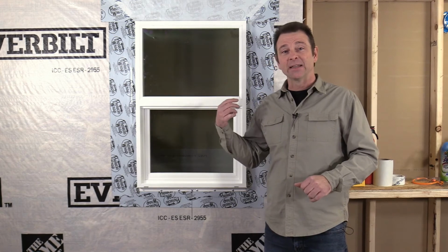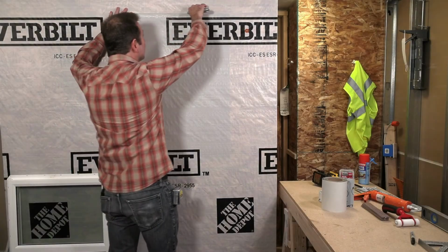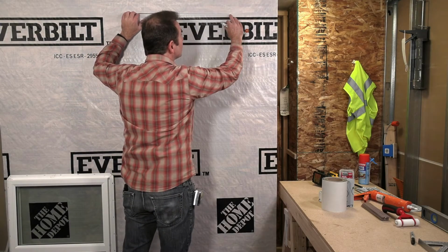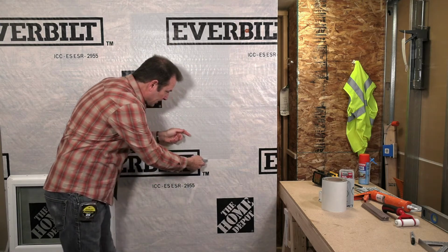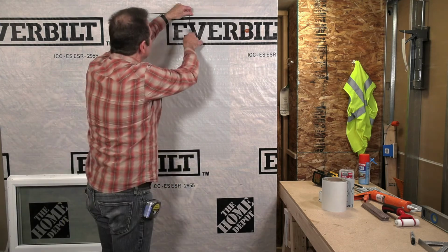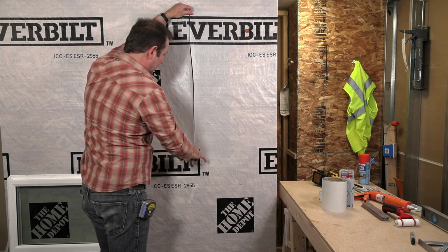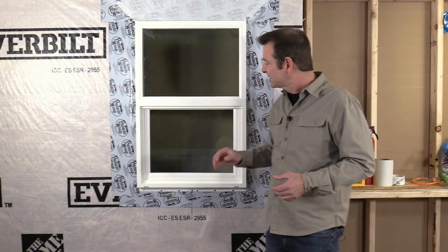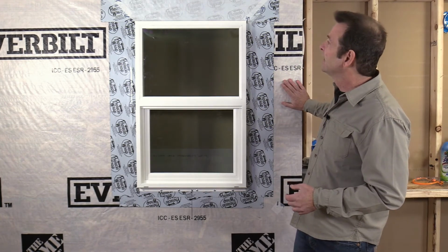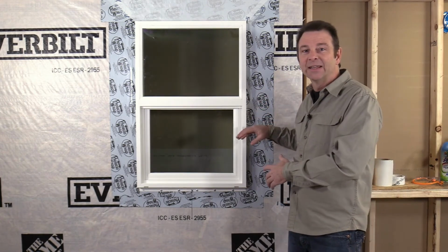So starting with the rough opening and the house wrap, it has to be cut in a specific way. We're going to use an eye cut, and we did that in the installation. You can see the cuts that you have to make will be flush with the top and the bottom of the rough opening, and then we're going to cut down the middle. All this gets wrapped in, and the purpose, we're trying to make this watertight. It starts with our house wrap, and then all of the parts will get added in.